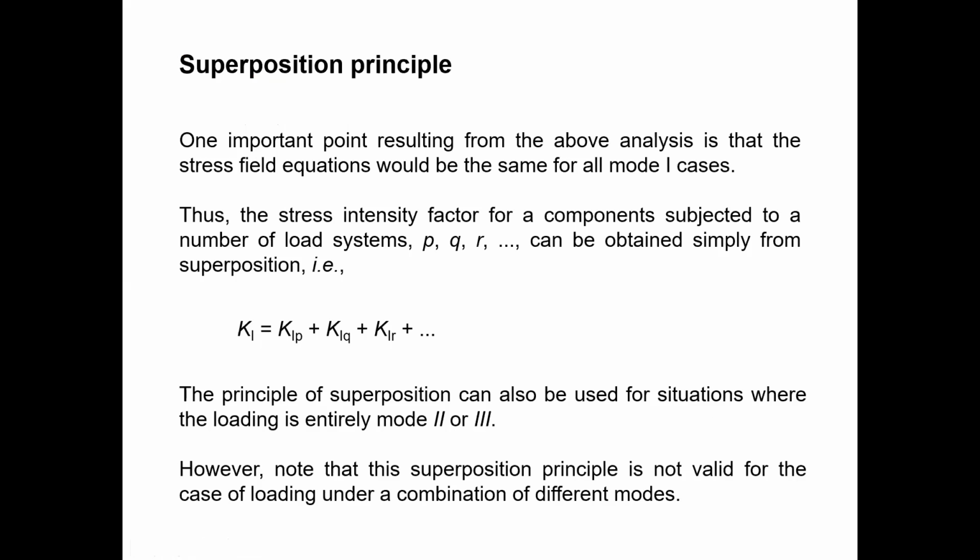So I will explain what the superposition principle is. Again, superposition principle applies in the mode 1 case. If we have different kinds of loading conditions, assume there is a PQR load, a generalized loading system, where P is bending, Q is torsion, and R is axial. Then you need to find out the axial Ki value, bending Ki value, and torsional Ki value, and get the summation. That is the superposition principle. I already explained that one.